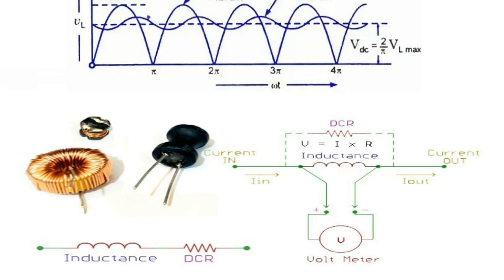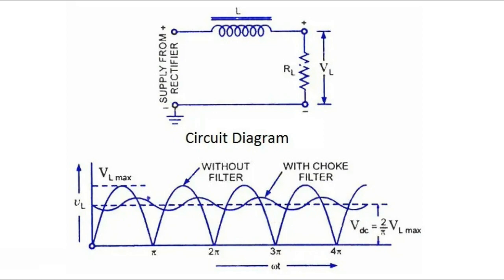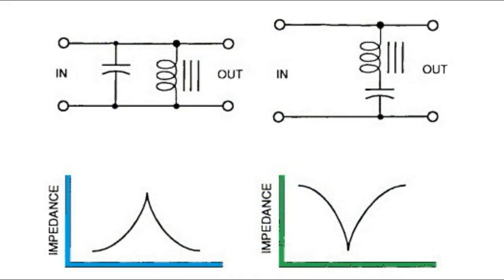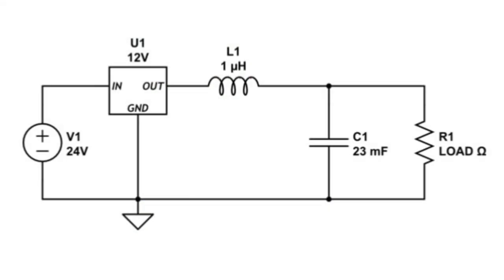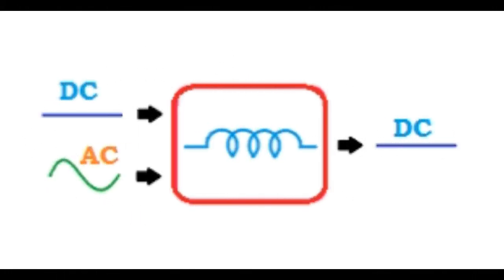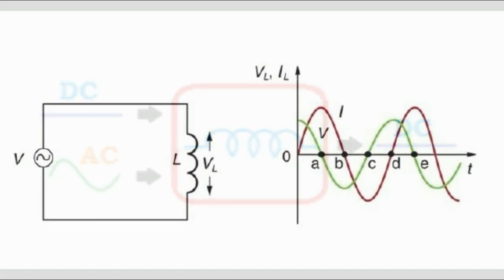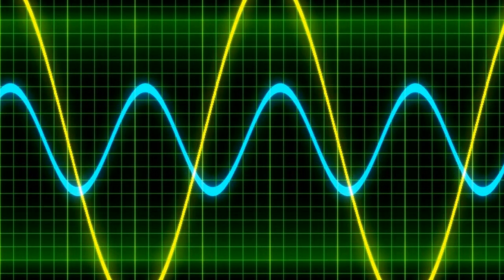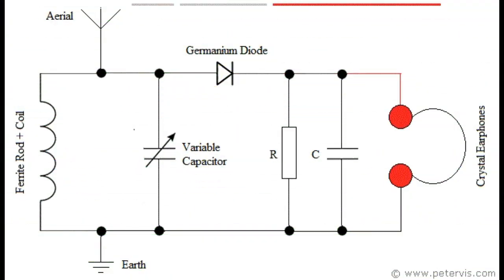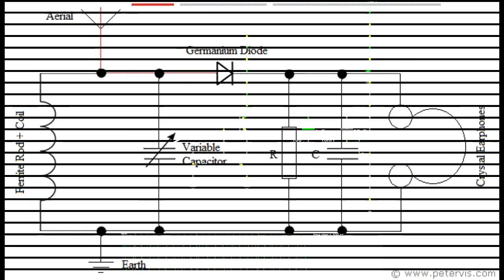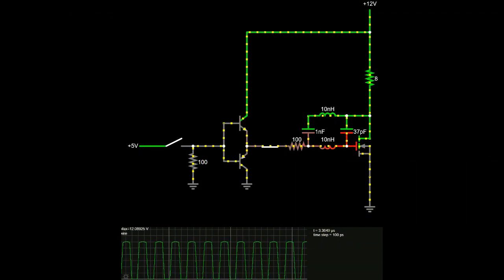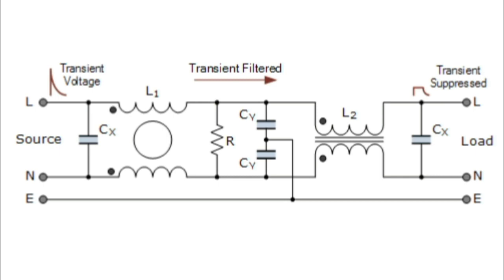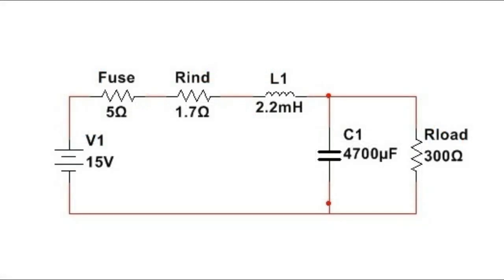Then the primary use for inductors is in filtering circuits, resonance circuits, and for current limiting. An inductor can be used in circuits to block or reshape alternating current or a range of sinusoidal frequencies, and in this role an inductor can be used to tune a simple radio receiver or various types of oscillators. It can also protect sensitive equipment from destructive voltage spikes and high inrush currents.